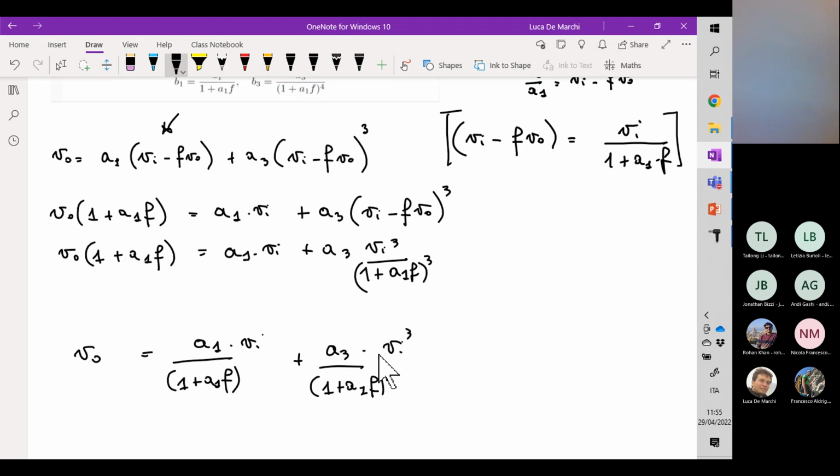Finally, let me discuss the case of phase margin equal to 90 degrees. In this case, the phase of the loop gain should be minus 90 degrees, and if we repeat the same analysis performed for the 45 degrees case, what we get is a certain reduction of the global gain with respect to the gain at DC.